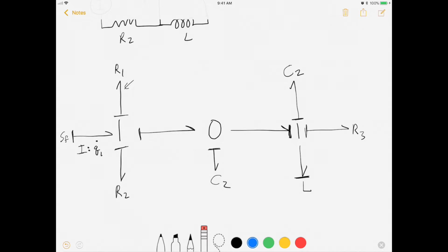So we're going to go through and ask, what does a capacitor have? Well, a capacitor has a charge. What's the relationship between charge and capacitance? You can tell right now that we can just put Q2 dot arbitrarily as the flow, and then we're going to say that the integral of that Q2 over C, charge over capacitance, is equal to voltage.